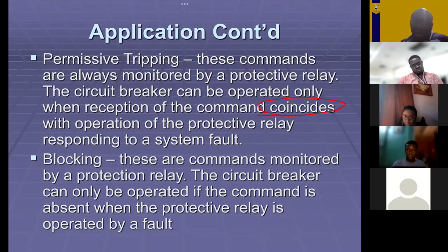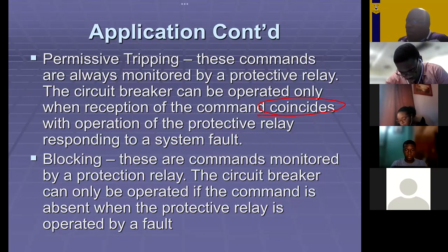Otherwise, there's nothing. So when we looked at the blocking scheme last time, what we saw was that the practical blocking scheme had a channel in-service monitor. So you have to ensure that the system required to send the signal is working at all times, because we are operating on the principle that I'm receiving a signal only in the circumstance that I have to block. Otherwise, we will operate.